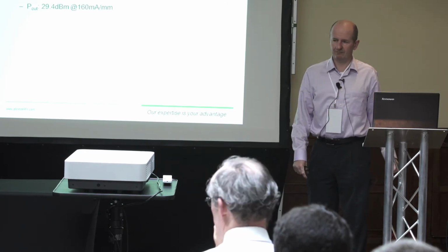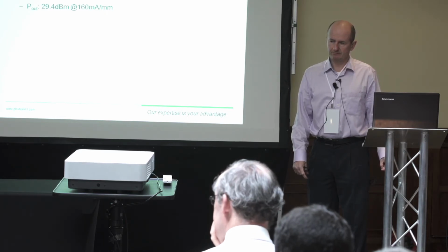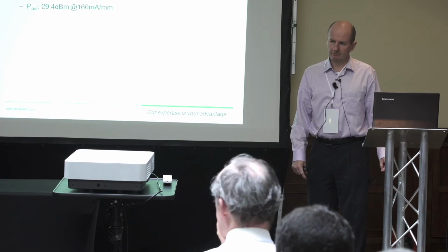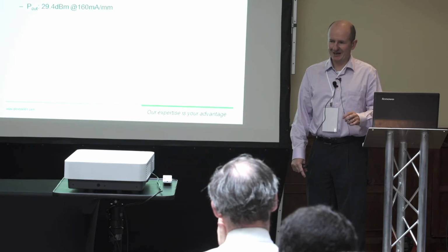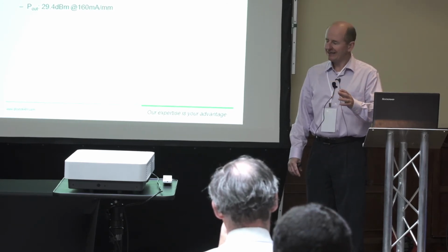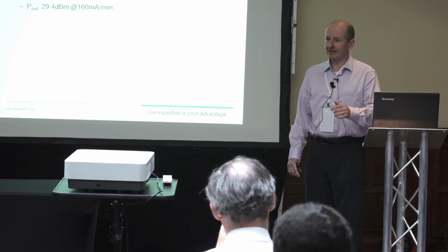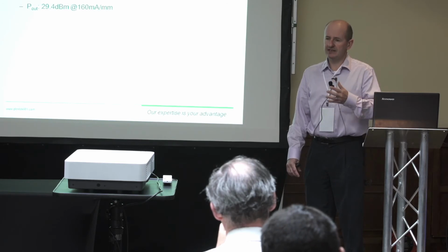Because you did mention or hint at the fact that GaN goes much more gently into compression than GaAs. But I just wonder what there is in the technology that allows it to be like that, or if that's not what you're saying. No, it's not at all. The actual fact that GaN goes softly into compression can be something of a pain. It can catch the unwary person out. You need to take that into account.